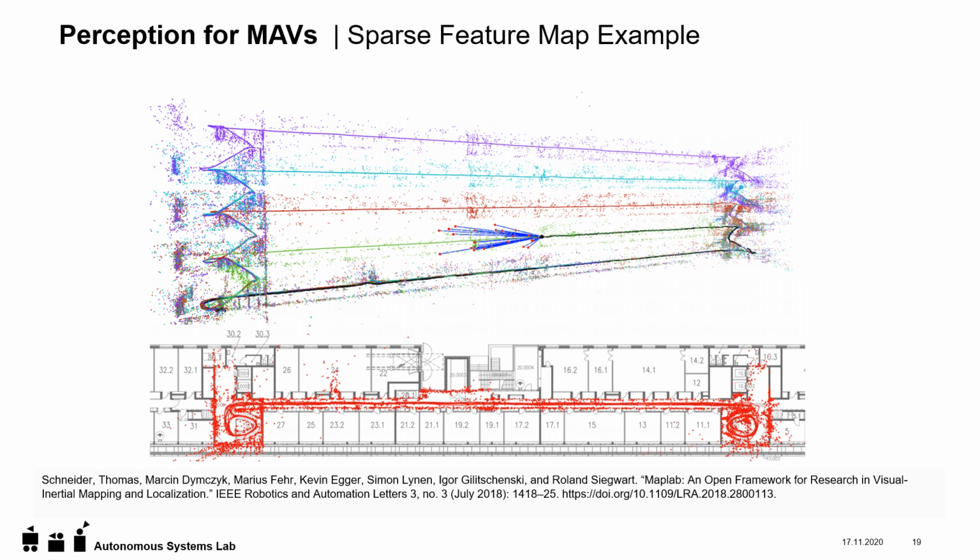And by doing multiple trajectories through this building and co-optimizing everything together, we obtain a nice, consistent, and also geometrically accurate representation of this building in terms of features. Below you can see an overlay of the feature map onto the building plan, which shows a very high consistency.